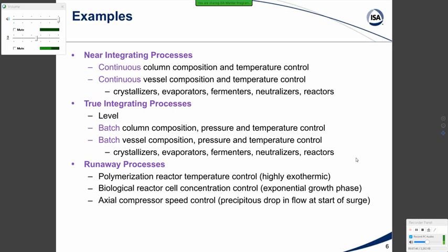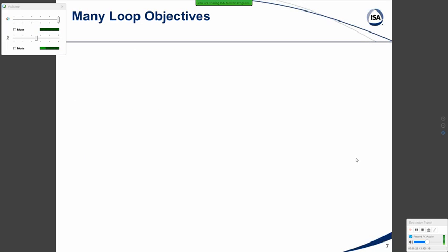Personally, I have seen compressor speed control accelerate, and the only way we could stop it, within a tenth or two-tenths of a second, was to look at the rate of change of speed and take an action to shut down the compressor before it damaged the rotors. As far as the PID controller sees, if you have a strong base, it doesn't really know what's happening beyond that, and it sees an acceleration as you're approaching the neutral point.